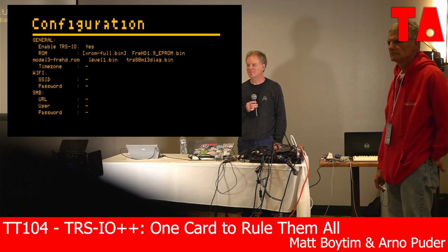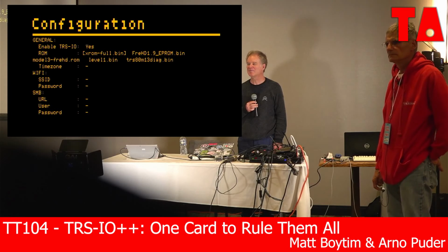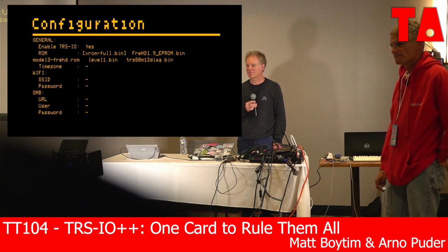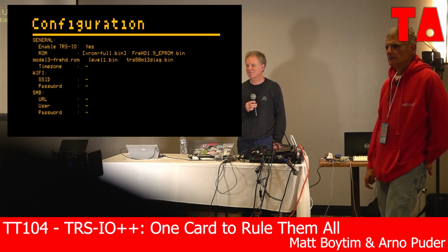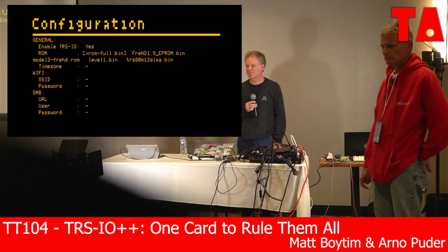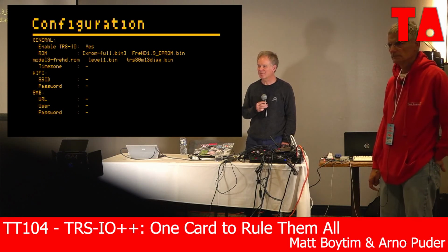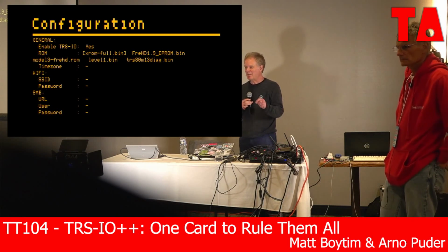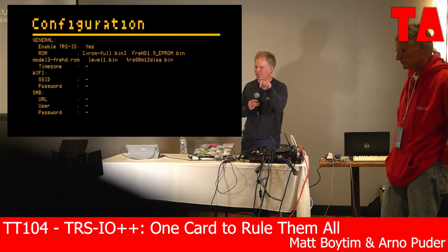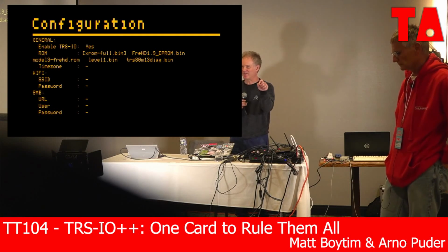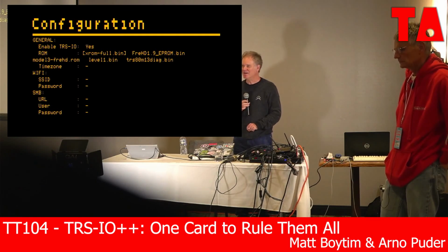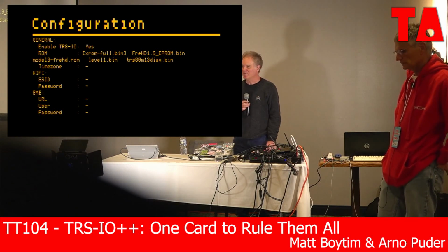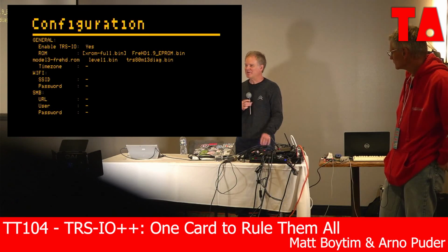Other questions? So the API that you were showing between the FPGA and the ESP, it seems like mostly it's the ESP requesting and the FPGA answering back. I just wondered if there's any capability to go the other direction, so that the FPGA could ask the ESP, hey, can I just use your ROM image over there, not even transfer it, and then free up the block RAM? Well, you remember there was one line that said request, where the FPGA can send a ping to the ESP. And then you have these 4 bits where you can say what you want. So yes, you could do that.